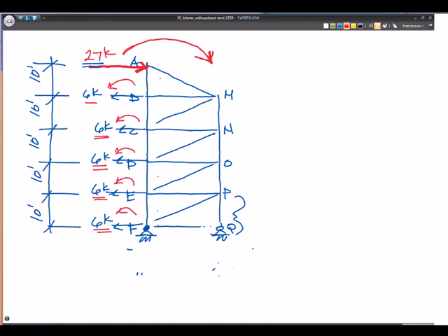Okay, so here is where we have to make that initial assumption. What are we assuming, and why I tipped it up so we can visualize this? If we have 27 kips tipping over times 50 feet off the ground, it's pushing this side of the frame down and pulling this side of the frame up. So I'm going to say as it pushes it down to the ground, that this has to go up.